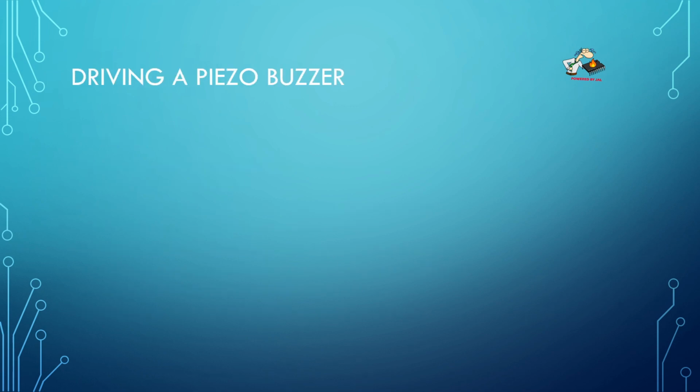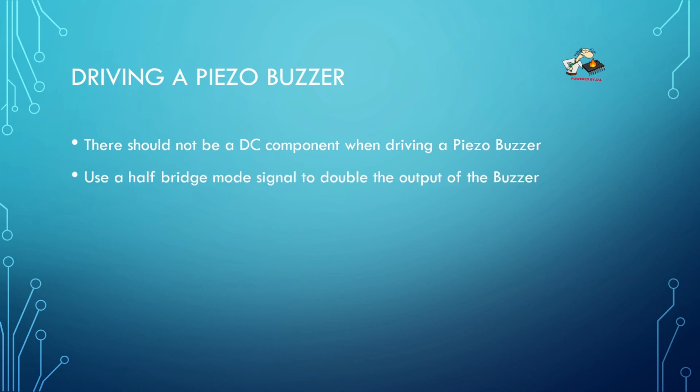So some information about driving a piezo buzzer. You should prevent a DC component, so there should not be any DC component when driving a piezo buzzer. And if you use a half-bridge mode signal, you can double the output of the buzzer and also the range of the buzzer. Half-bridge mode signal means that you have two pins. When one pin goes high, the other pin goes low. And the PIC microcontroller can generate such a half-bridge mode signal.